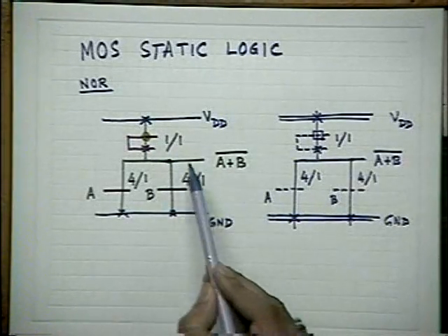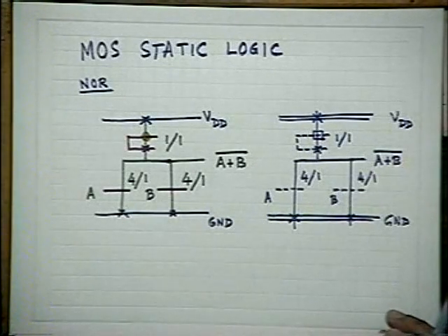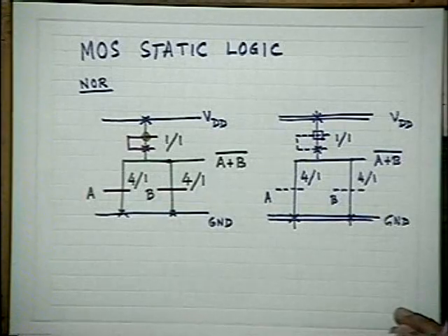Please don't assume that, normally, the channel length is kept the same. It is the W which is adjusted. Please remember that this is a tendency, today's technology demand. Earlier it was not like this, because earlier all MOSFET logic was limited to several megahertz.